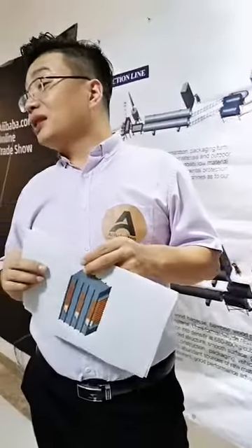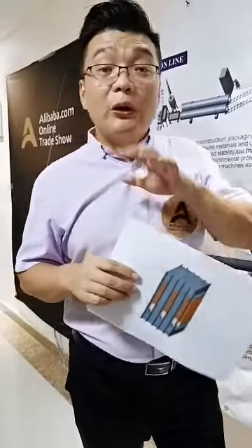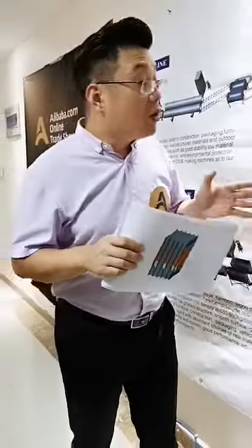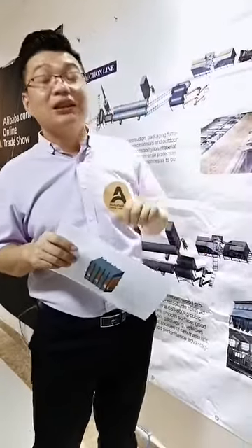And the thickness of the hot plating is also a big difference. For plywood, the common thickness we can see is maybe 42 millimeters or 52 millimeters. But for a particleboard hot press, the common hot plating thickness is 120 millimeters. It's very big, very thick. Why?